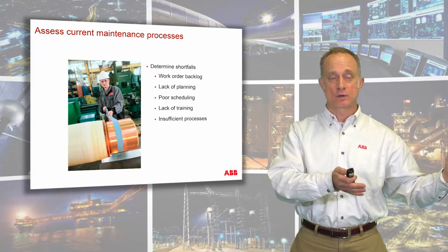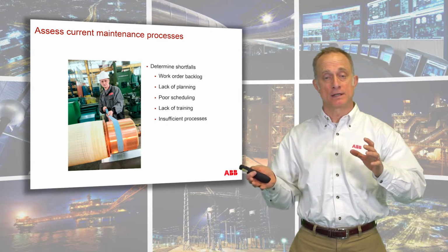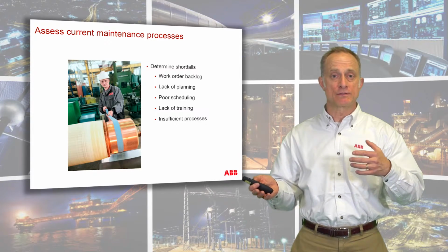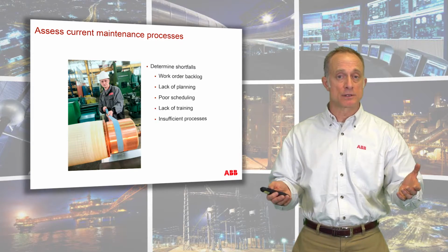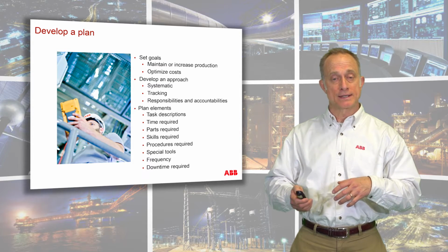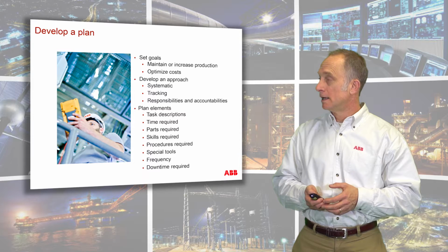After you've done that criticality analysis and the failure modes and effects analysis, you might have identified areas where your processes just wouldn't allow you to really effectively act on the recommendations that you just put together as part of the failure modes and effects analysis. You want to put together a plan then to address those areas that might be weaknesses in your processes.